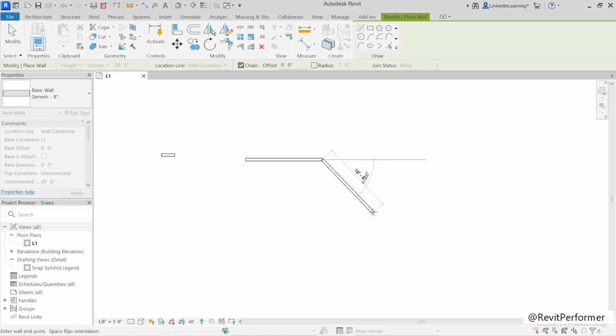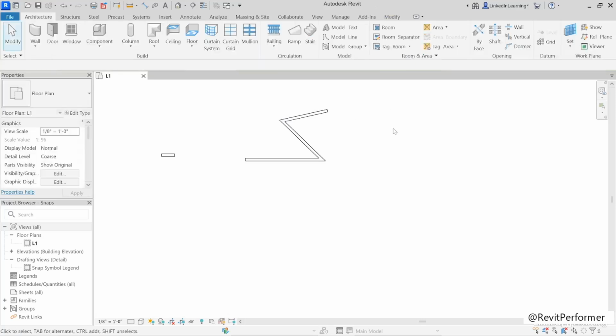However, there are also some built-in angles which are useful to us. 45 degrees, 90 degrees, horizontal and vertical, right? So you can snap to any of those preset increments just simply by clicking when you see that little indicator on screen, or knowing that even if you're going at some random angle, you're never at a fractional degree, you're always at a whole degree increment, right?